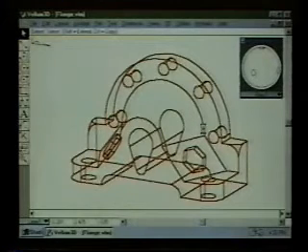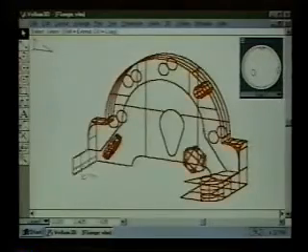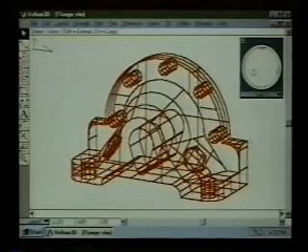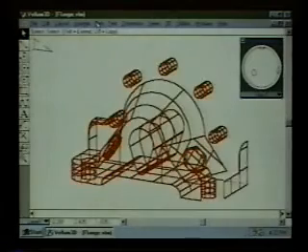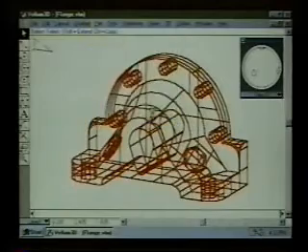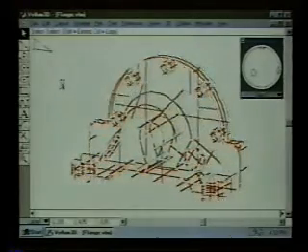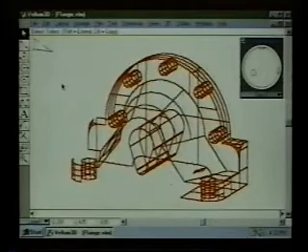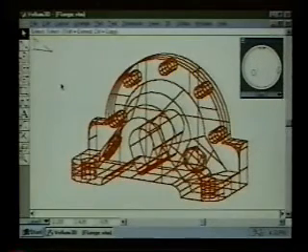And the great thing about the auto surface is that it generates all the object surfaces automatically, the holes and the curves, and then these are all NURB surfaces that you can take out to other programs for doing rendering and animation, and also to manufacturing and milling. So now that the surfaces are on here, I can go and change the color of this object to something like magenta, and then I can show this either as a wireframe as we see it now, or I can do automatic hidden line removal on it, and I can also do perspective and color shaded views as well.